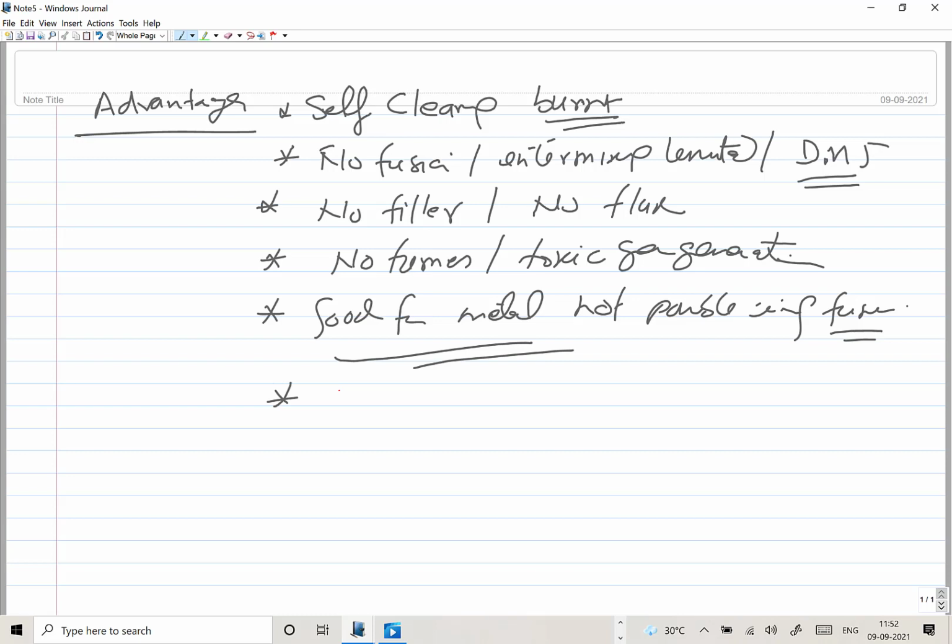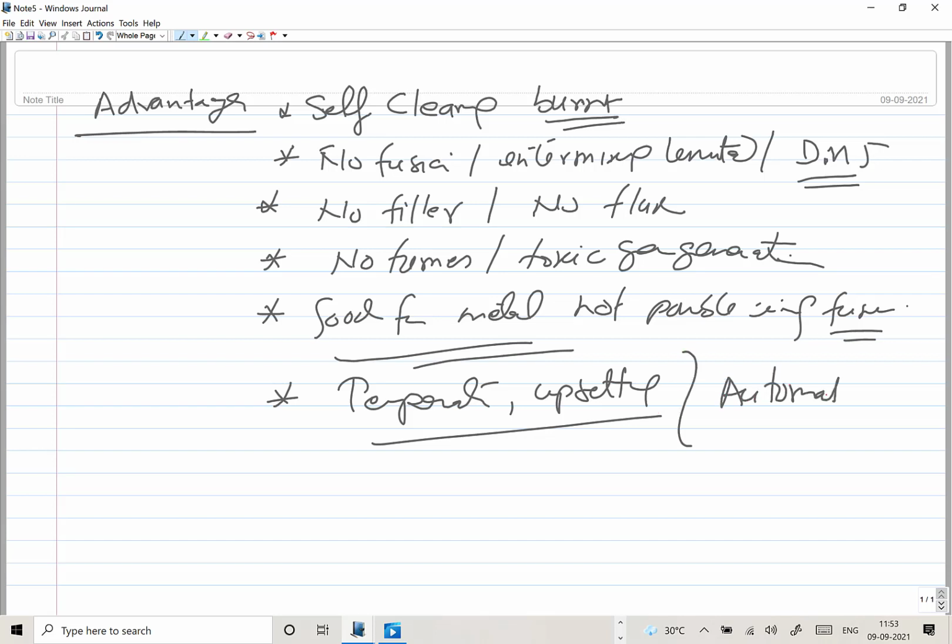But if you see, in these cases where the fusion is to be realized, there can be a lot of inconsistencies. In friction welding, you can have control over the temperature to be achieved and the kind of upsetting. So you are aware of the kind of temperature that needs to be realized and the kind of upsetting to be done, and accordingly you can identify different parameters to be used, and because of this the automation of friction welding is very much possible easily.